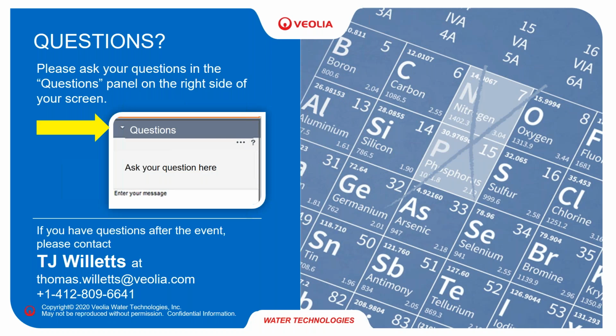And it could, at very high concentrations. TDS, like any salt, at first would start retardation of biological processes, so the processes become slower, and then at some point high salt concentrations would fully stop the biological processes. So it's highly dependent on your concentration.